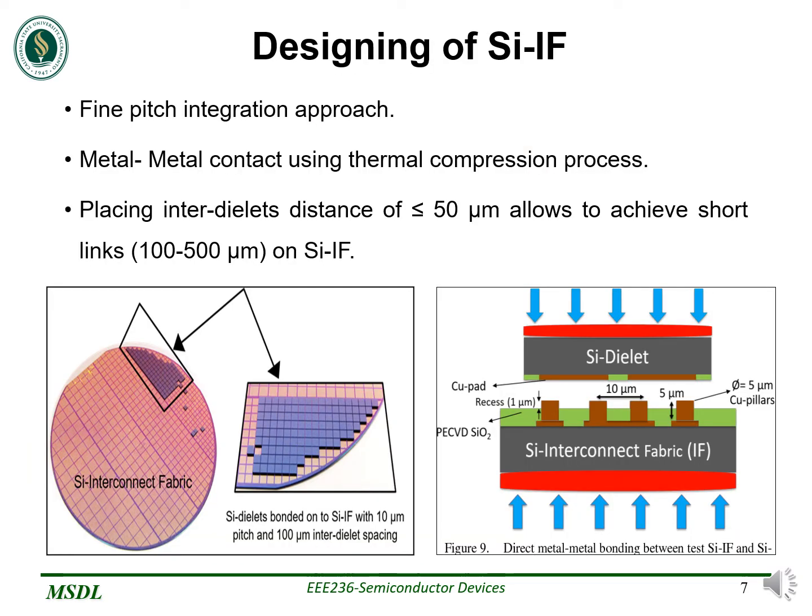In this slide, we can discuss the designing of silicon interconnect fabric. For the designing of silicon interconnect fabric, we can use the fine pitch integration approach, which allows us to integrate heterogeneous dies on a silicon-based platform. The interconnect pitches on silicon interconnect fabric are similar to the fat wire level pitches of a microelectronic chip.